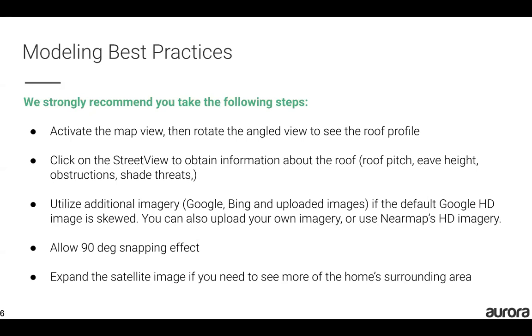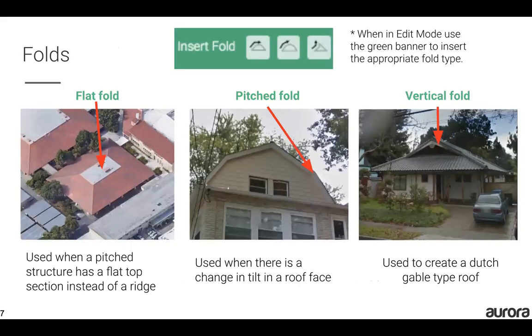corners. And then lastly, if you do need to expand the satellite imagery, you can move your cursor to the outer edge of your satellite image, left click, and that will expand it a little bit at a time.